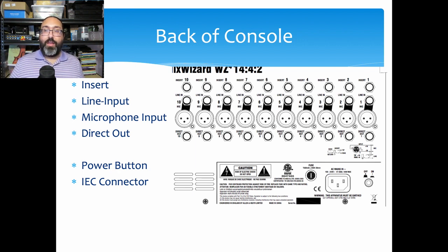Now, again, key thing with this Allen & Heath MixWizard: if you want to use that line level input, you need to press down that pad button. Otherwise, the line level will not activate and will not work, and you will not get any sound no matter how well you plug it in.